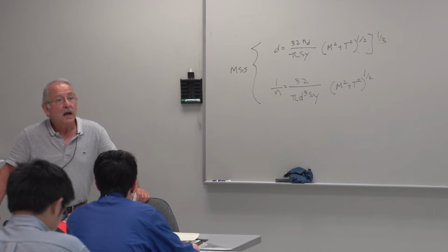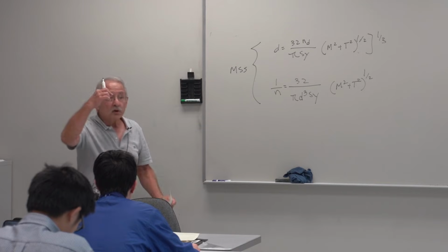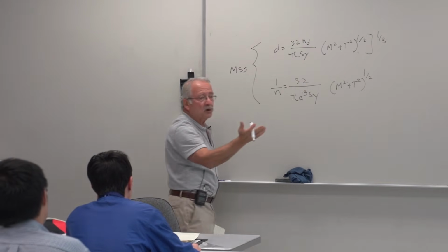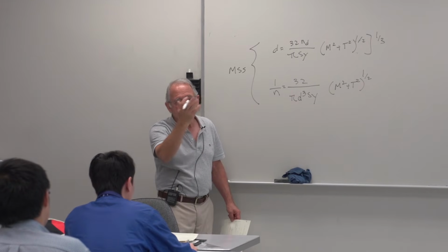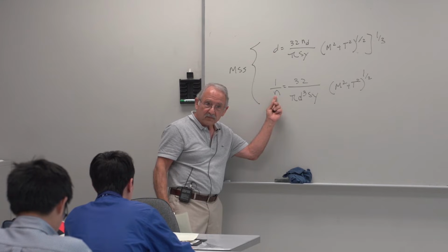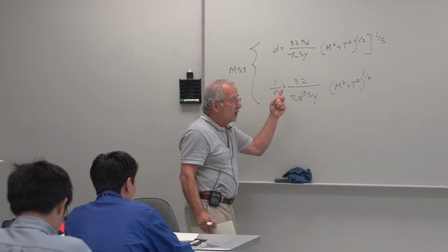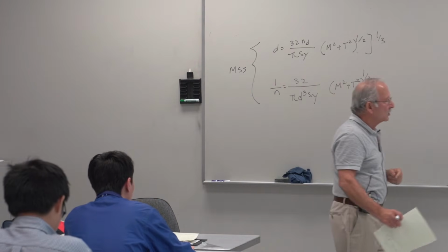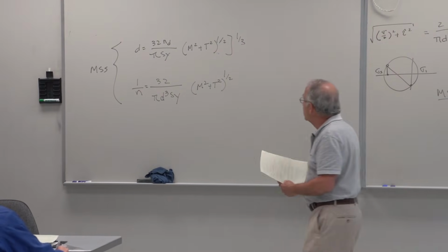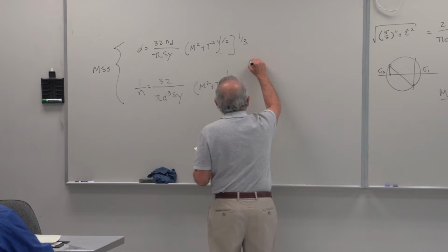higher size. As you do so, the original design factor, which was 2, has now been increased to 2.2, 2.5, whatever. That's this factor of safety. That's the difference between the two. And the design factor is less than or equal to the factor of safety. A similar set of equations for MDE.